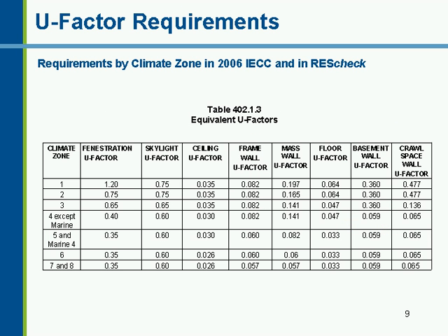The second table in the 2006 IECC, and what is in REScheck, is the U factor table. Another point to make here is that REScheck uses the U factor table. This is for the entire assembly component, for that individual component. The other table was your insulation values only. So when you're looking at the other table, you're looking at R values of insulation for the particular component. This one is the U factor of the entire component. Also, what's still applicable that's not in this equivalent U factor table is your solar heat gain coefficient requirements. They still need to be met depending on your climate location, and those fall under the other table, the R value table, as I shall call it.